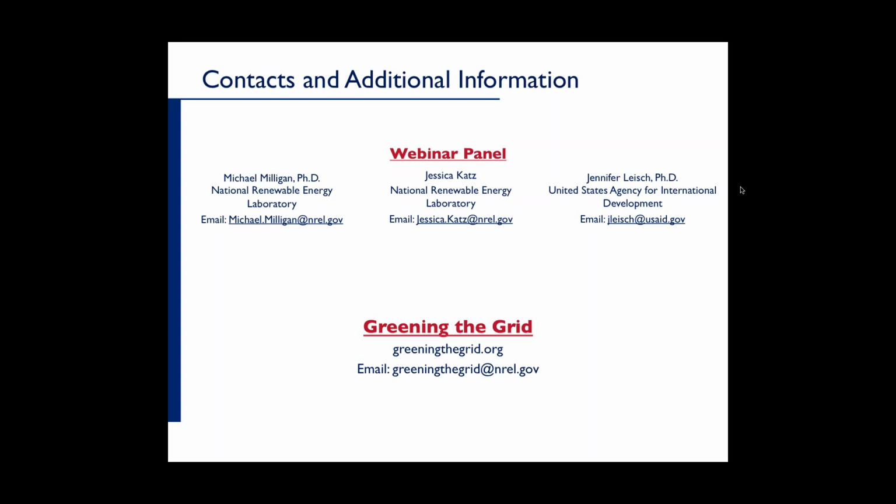Primarily, and I don't know if this is true in all parts of the world, but I know it's true here and in many parts of the world, the distributed PV is not visible to the power system operator. So I'm running the transmission system. I know where all the large generators are. I know what the transmission line loading is. I know what demand is. Actually, I may not even know what demand is because now if I have a lot of solar PV on the distribution network, I can't really tell if a cloud has come by and reduced solar output or if somebody just turned on a big massive load of some kind.